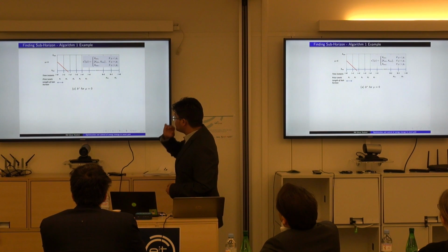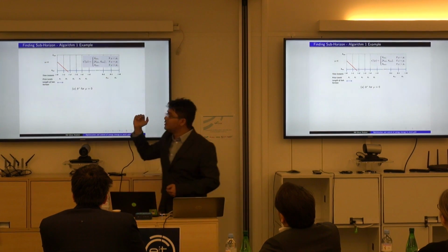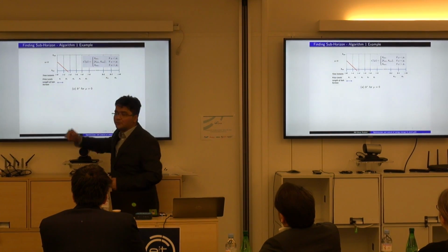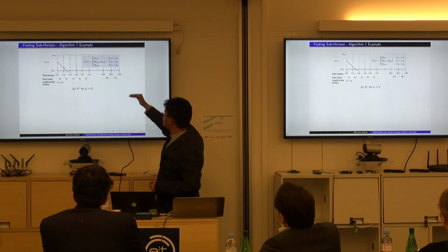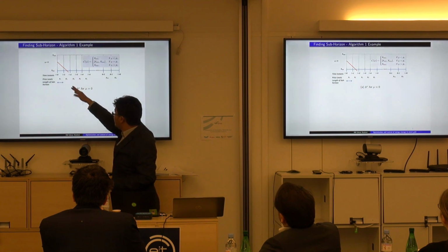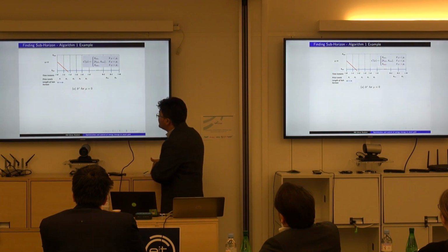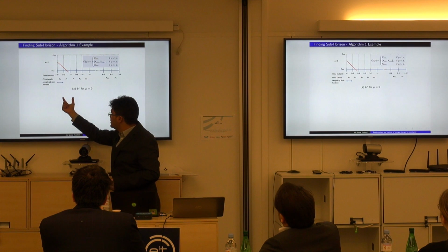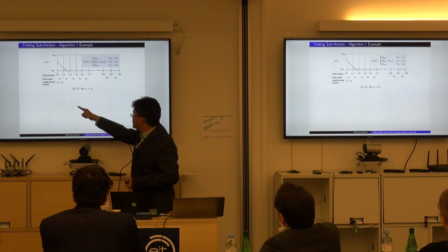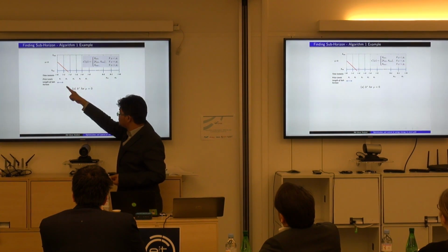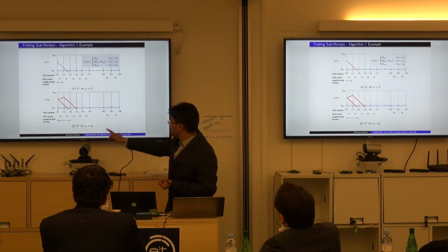So consider prices are in ascending order. P1 is lower than P2 and so on. For the first case, we initiate our algorithm from mu equal to 0. If we see these threshold-based levels, then the battery should discharge at the maximum rate. And what we see is, between i equal to 1 and 2, the battery capacity is violating the lower boundary, and the new subhorizon, this is like a temporary subhorizon that we identified, has only 1 point. So the next jump from mu equal to 0 will be to the next price level in the subhorizon that we already identified, which is mu equal to P1.